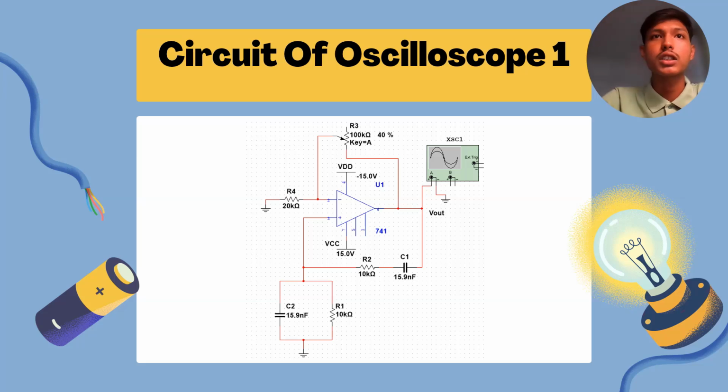So this is our circuit of oscillator 1. As we can see in the circuit, they have three resistors and one variable resistor, and they have two capacitors. Also we use an op amp. The type of op amp is 741, and we can see a Wien bridge oscillator must have an RC series circuit and an RC parallel circuit.